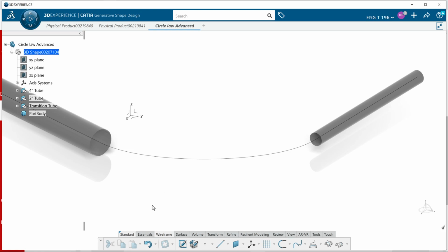And all I did was recreate my geometry so all the flow is going one way, and then all of a sudden it does work. So in theory, that shouldn't be an issue. It shouldn't be anything that I have to worry about. In reality, I have run across it a number of times where that was the issue, and it was painstaking to find out that that was the issue, because it really shouldn't be an issue as far as I'm concerned. But I'm just trying to make a point of creating things in a logical order. If that's going to be the flow from left to right or counterclockwise, then I would try and create everything to flow that same direction. Okay?